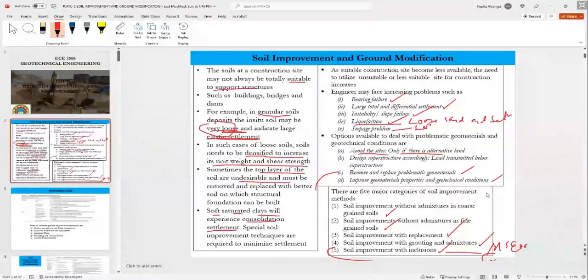So mechanically stabilized earth walls are earth walls with reinforcements in them. They can be metallic reinforcement, which is inextensible reinforcement, or geosynthetics, which is extensible reinforcement. So we're going to do a couple, and probably for MSE walls, we will push that to the topic of geosynthetics.